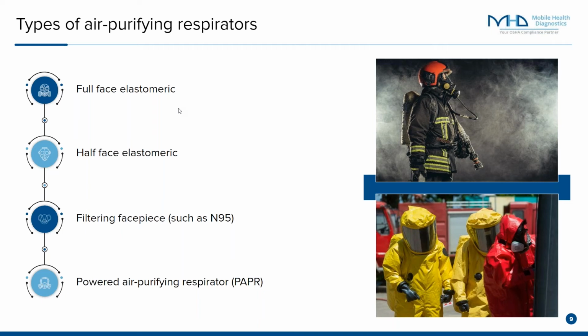So, one thing to keep in mind with powered air purifying respirators, generally, they don't need to be fit tested. Again, you want to verify that with the manufacturer. All manufacturers have instruction manuals that'll help you determine whether a fit test is needed. But the other types of respirators, the full face elastomeric, the half face elastomeric, and the filtering face piece type respirators, are tight fitting to the face, so they do require an annual fit test. So do keep that in mind.